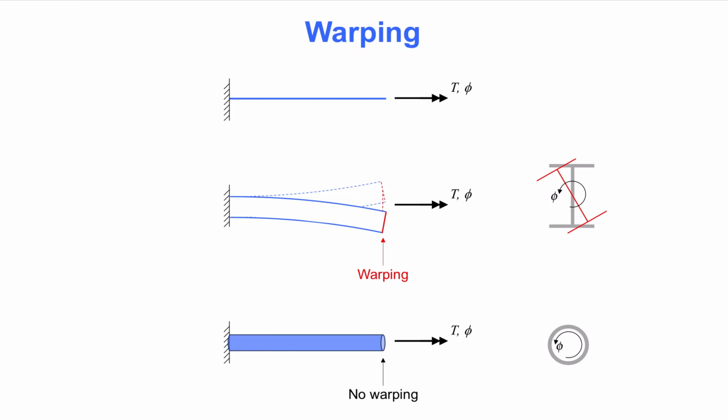Next, we turn our attention to the left-hand side, where the beam is completely fixed. Observe that the upper flange, marked with solid blue lines, is bending like a cantilevered beam. Similarly, the lower flange, marked with dashed lines, is bending in the other direction, also acting as a cantilevered beam. From Euler-Bernoulli beam theory and simple structural analysis for a cantilevered beam, we know that a bending moment and associated axial stress develop at the fixed end of the beam. In other words, the beam wants to displace in the axial direction at the left end, just like it is allowed to do at the other end.